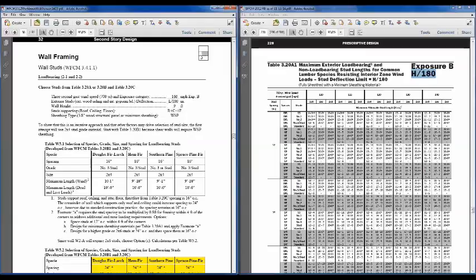And over here on the left-hand side is a master bedroom with a vaulted ceiling. And so we'll be looking at 2 different designs accounting for 9-foot walls and a normal flat ceiling in one, and then a vaulted ceiling on this left-hand side. So we're carrying a roof ceiling and one floor above these wall studs, and the sheathing on the exterior is wood structural panel sheathing.